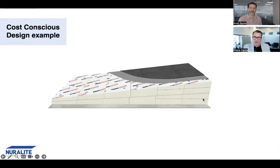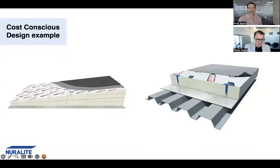So we went through about 5 or 6 different iterations with the designer, still trying to aim for what they wanted, the high R value and the thermal performance, and all those types of things. So to cut a long story short, we ended up saving $350,000 just in insulation alone, or about $250 a square meter, by going to a metal tray substrate which actually had the fall in it. So we weren't using tapered PIR, we were using flat PIR board. And then we were able to use an 80mm flat insulation board to give them the R value that they required that came out of the thermal modeling.